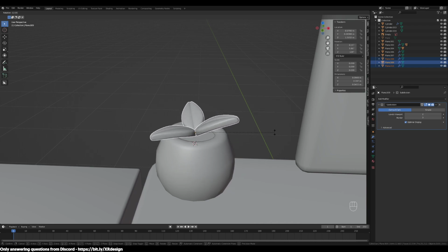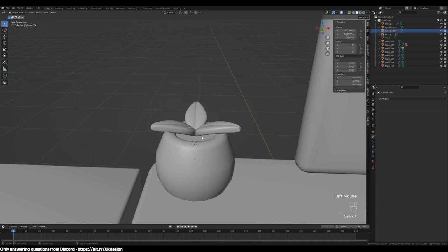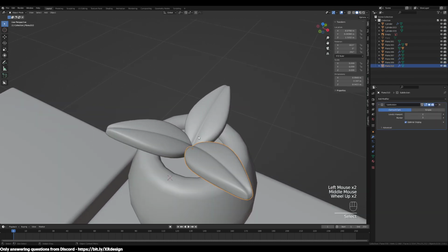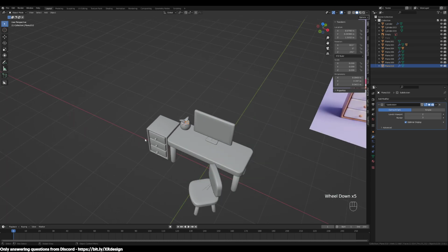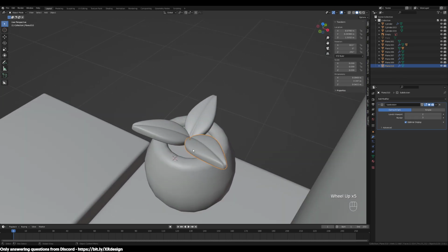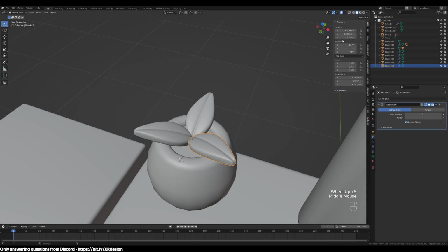What we want to do is rotate it along the local x-axis of each object, meaning there's a concept of global axis, which is these 3 lines in Blender, but then per object, there is a local axis. So for this one, we've rotated by 240. If I wanted to see the local x-axis of this object, I can hit R X once.